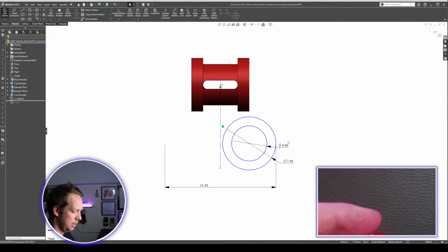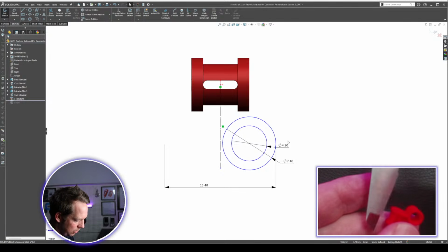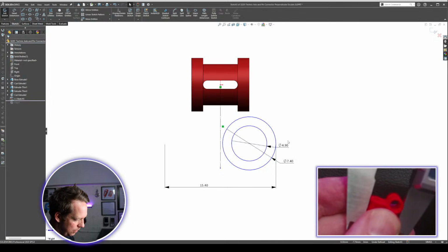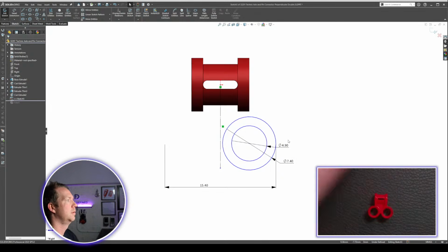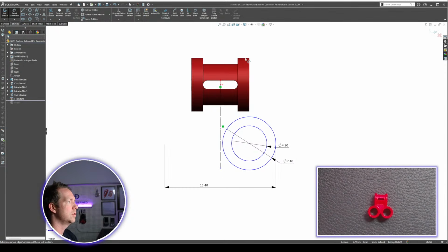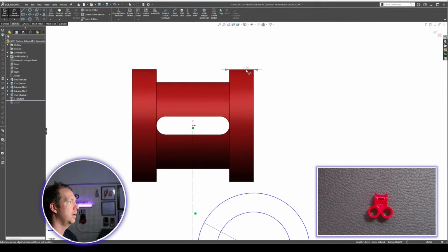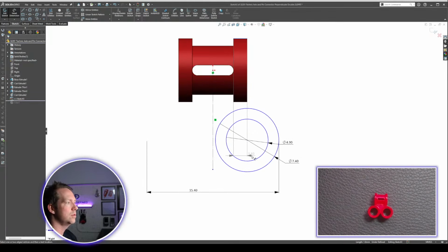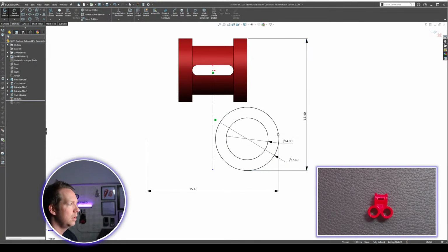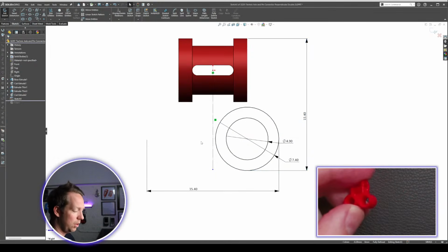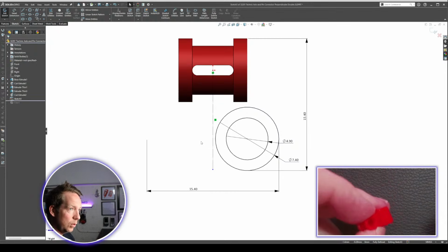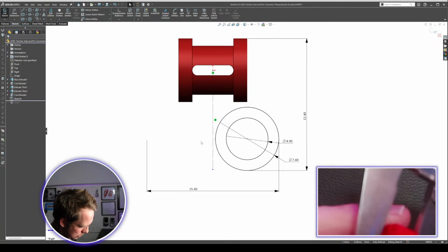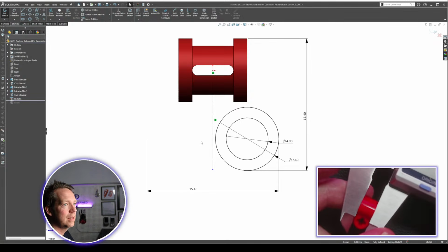And the next job is to do the height. For the height, I can do the opposite, just rotate it around 90 degrees. I can see that it's actually the same dimension, 15.4. And so from here, I can do the top edge. Now, it can be difficult to select sometimes, you just have to get really close. Shift on the bottom, 15.4. And now that circular component is fully defined. The width of this is going to match the top part, which is 7.8.